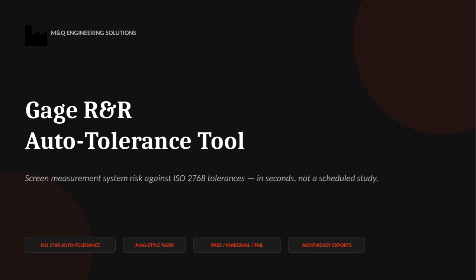It's important to understand that this tool is meant as a preliminary screening aid, not a full replacement for a detailed AIAG measurement systems analysis study. The tool itself displays a clear note stating this. However, it's incredibly effective at catching obvious issues, like a worn micrometer or a fixture with too much play, in mere seconds, saving you the time and effort of scheduling a formal study.